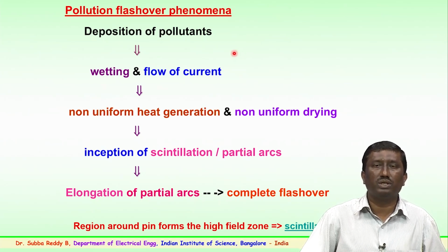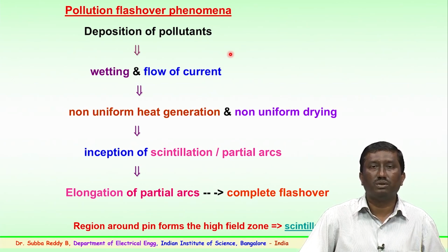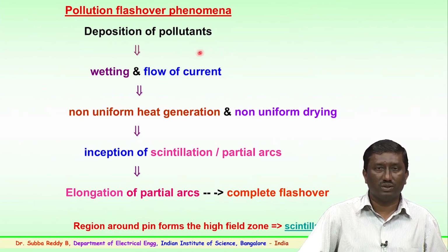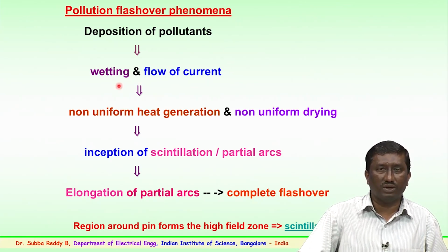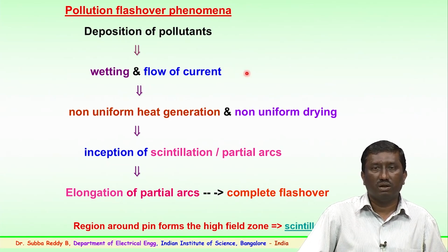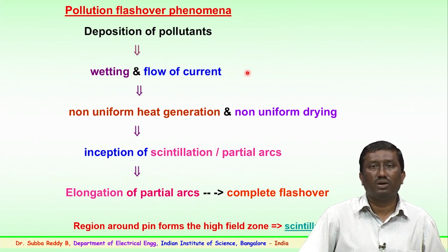It could even wash the pollutants off the surface of the insulator so that the flashover may not happen, or it could also bridge the flashover between two sheds. So, rain is a complicating factor, but fog, dew, light rain and mist are very unwanted and dangerous events which could trigger the pollution flashover, because they wet the surface, the surface becomes conductive, and a leakage current starts flowing on the insulator from the conductor towards the ground end. The surface condition dictates the flow of current.